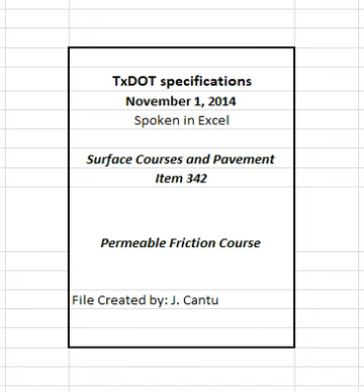The engineer may determine the gradations based on either washed or dry sieve analysis from samples obtained from individual aggregate cold feed bins or aggregate stockpiles. The engineer may perform spot checks using the gradations supplied by the contractor on the mixture design report as an input for the template. However, a failing spot check will require confirmation with the stockpile gradation determined by the engineer.